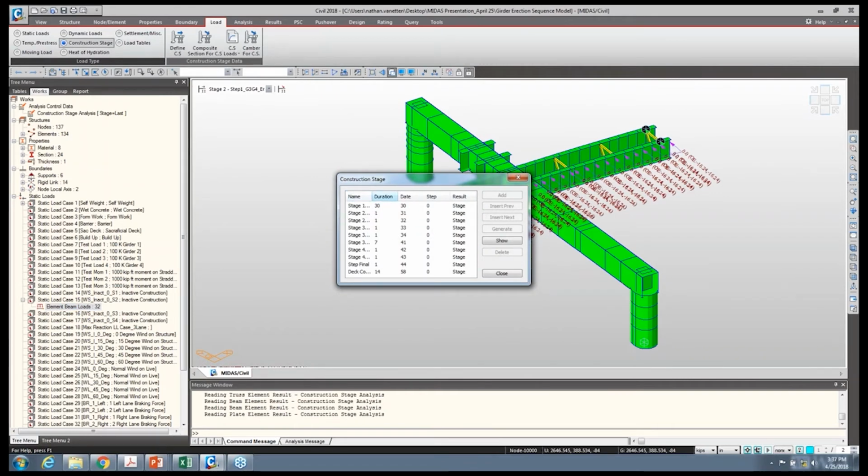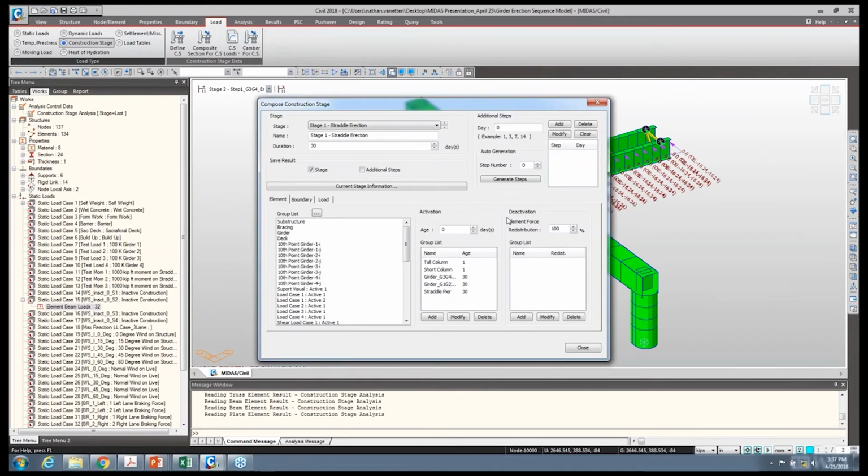So what you'll see is a series of sections. And as I go to the towers removed, the thing I wanted to show you is that it's also possible to deactivate conditions. So in this particular case, I am actually removing some of the temporary towers that are used to support the structure. And that can be seen once again as we work our way through visually. Here it is with the towers removed. Here's the section with the towers. So between there, I am deactivating those conditions, and that is creating our construction stage.